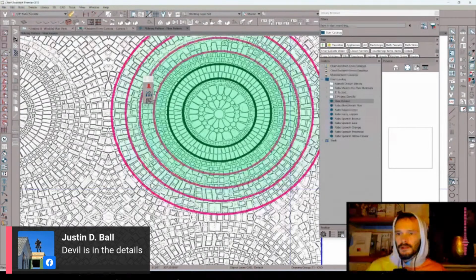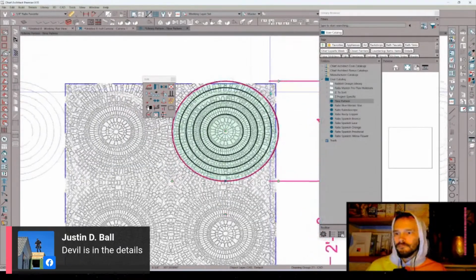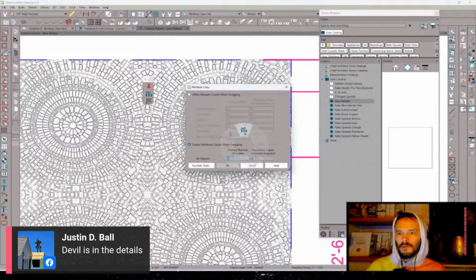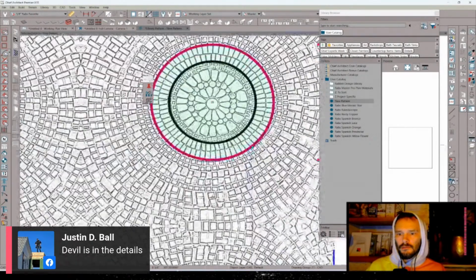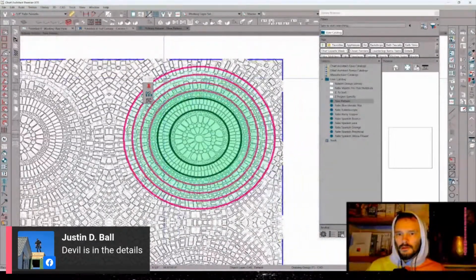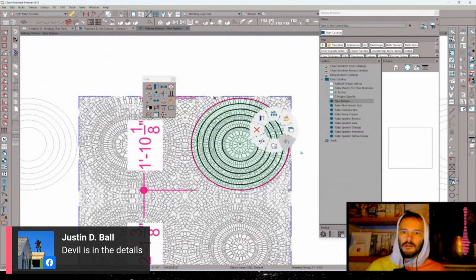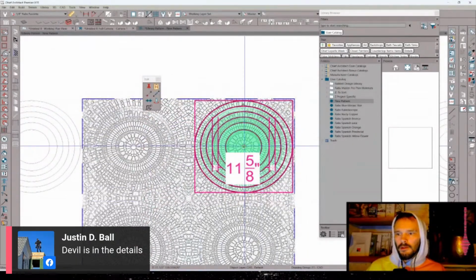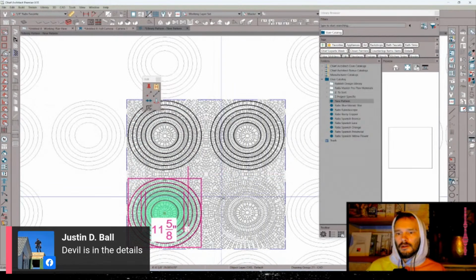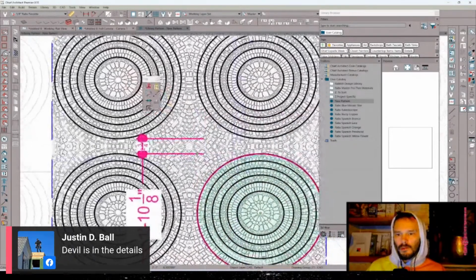And we're just going to get close, and that's it. It's going to be representative, right? And let's back out of that because I don't want it to go over the top of the outside of this. Making sure that it's just within that one right there. That's good. Okay. And then I can marquee select similar, select all these, copy it, reflect about center. Simple enough. Copy it, reflect about center, copy it, reflect about center. So getting really close. Let's just do one more copy.